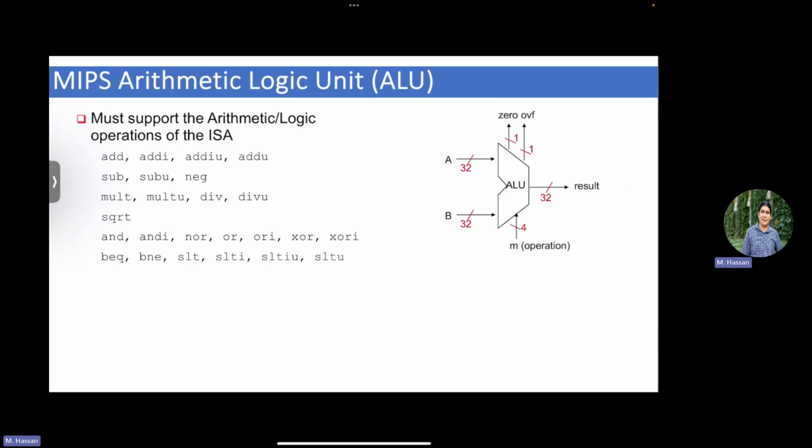So you do the sign extension if your offset is signed, because if it is signed, it means that the most significant bit is the sign. So if it's 1, it means it's negative. Now, if I 0 extend it, I mistakenly transform the number from negative to positive. Right? So I cannot really 0 extend the signed number. What we do is sign extension. You take the last bit and replicate it, right? If it's a 1, it's a 1. If it's a 0, it's a 0. It's called sign extension of a number, right? And we need to sign extend our offset before adding it to the program counter. Okay?